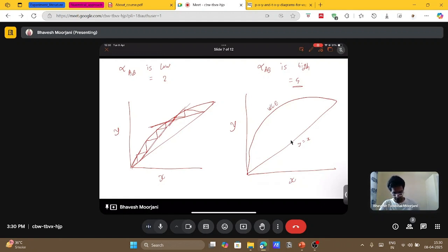So these are the theoretical stages. Now for the same operating line condition, if you have a greater relative volatility, the number of stages required to achieve the same separation will go down, right? So you can see we can achieve the same amount of separation in 3 stages compared to 1, 2, 3, 4, 5, 6 stages here. Okay. So that's the difference of relative volatility on your distillation column.